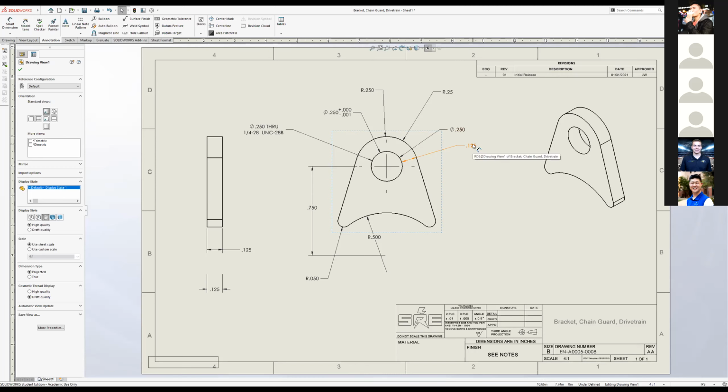Yeah, and I found that in industry, if you send a drawing, typically that is the holy grail for that part. Basically, it's blueprint. So even if you send a step file, they still have to build it to the drawing, and the step file would only be used as reference. Now that's only some cases.